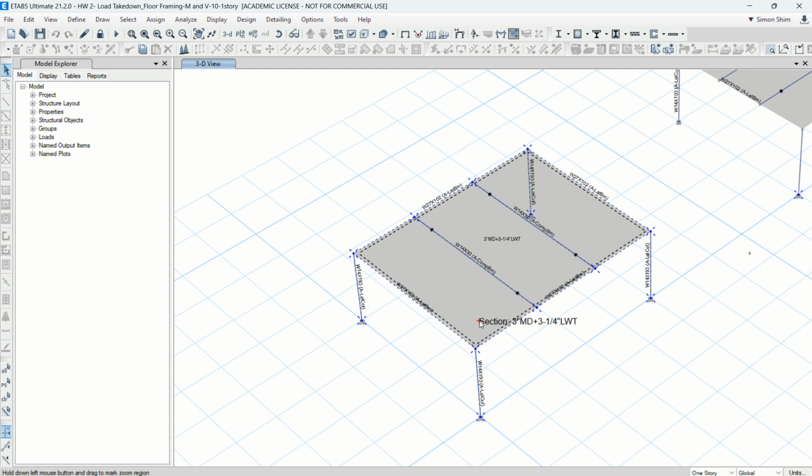In order to do that, we need to reduce the moment. This is more of a numerical feature, in order to make the analysis run based upon what we need. Typically designers try to define the moment restraint. So just the last one, click the beam.